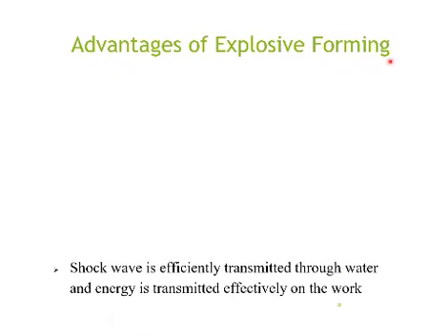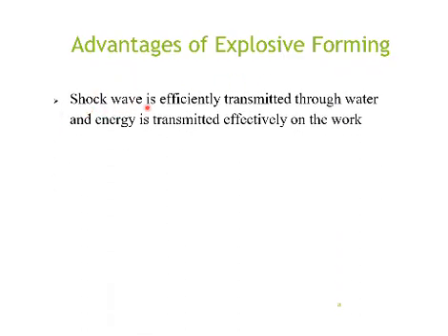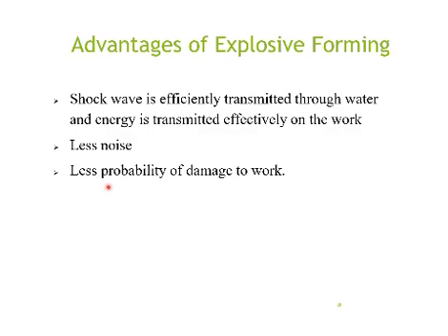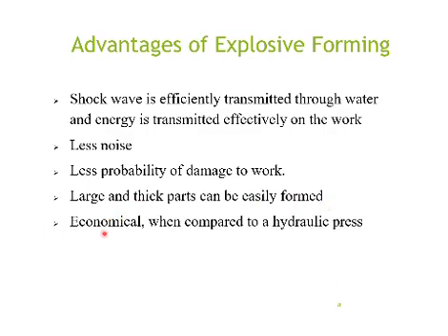Now we see the advantages of explosive forming. The shock wave is efficiently transmitted through water and energy is transmitted effectively to the work. Less noise is produced during this process. Less probability of damage to work. Large and thick parts can be easily formed. Economical when compared to hydraulic press.